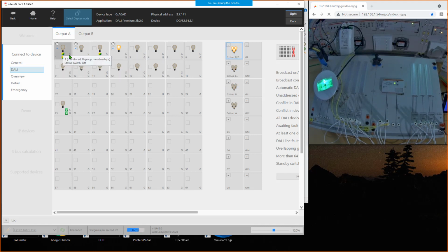Because today, you do the settings of this ballast 1, 2, and 4. And tomorrow, if you want to continue and you want to change the address, by chance, nothing happens because this device here is fixed to the address number 4. Only if you untick it, then of course you can change the address.